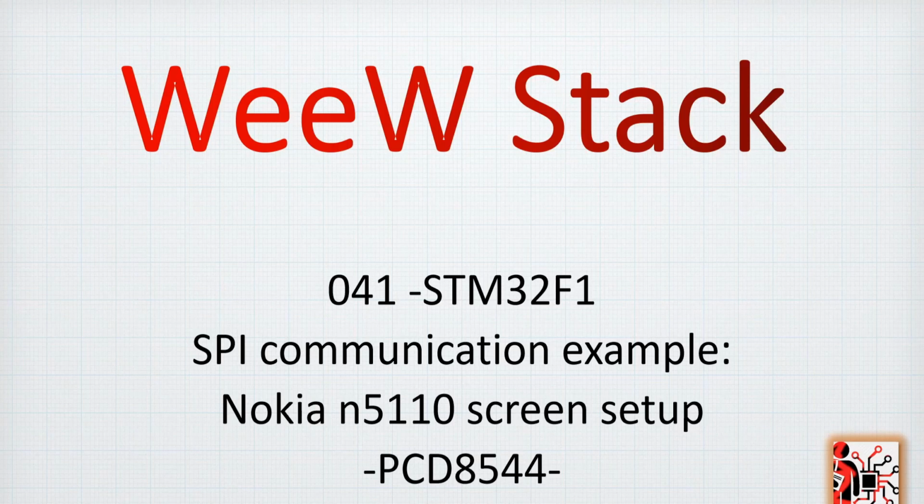And so we have been looking so far at SPI communication on the STM32F1, but really we should have a good example, and today we are using the Nokia N5110 screen. I think I'm a bit too old, so I know it very well. The part number, the SKU, is the PCD8544, so we have this SPI communication. Good, so let's take a look at it.